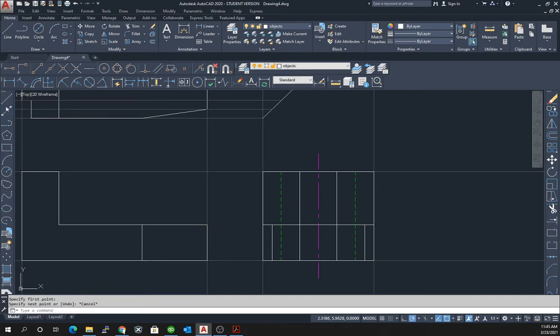Actually there are two ways to do this. We can actually type it, or if we set with 30-degree angles, which we actually are, we can choose line. And then remember, this is 180, so if we want to go 30 degrees beyond that, we'll be at 210. So we can simply draw a line just like this. So an angle of 210. And then we go on the other side.